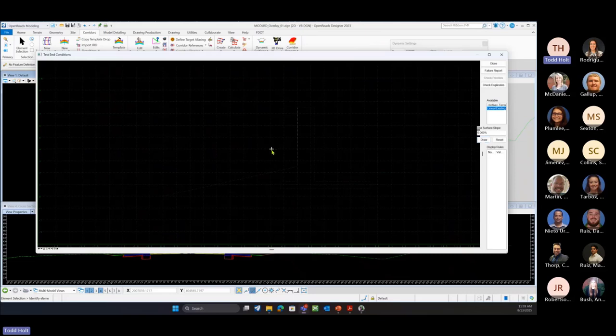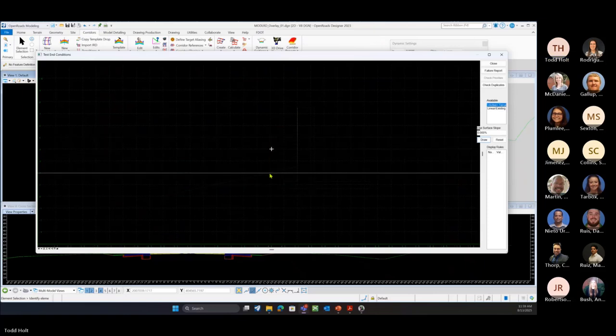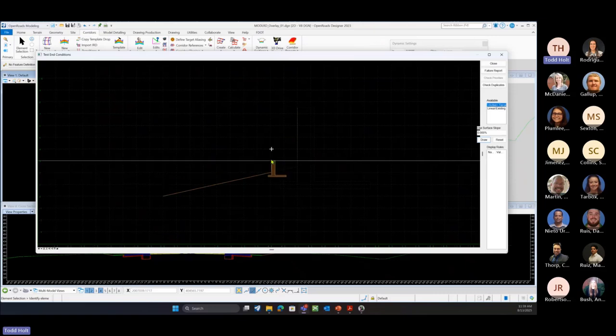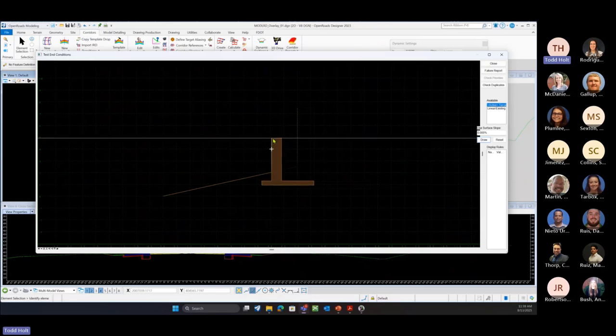So if we find that wall feature, and then if our other criteria finds existing ground, that search criteria is going to go up to it and find that, and then we can have a variable height wall put in. Because we're going to search out to that point, finding the feature definition, and then up from that point, that's going to define the height of our wall. So that's what we're going to build in and get that solution in there.